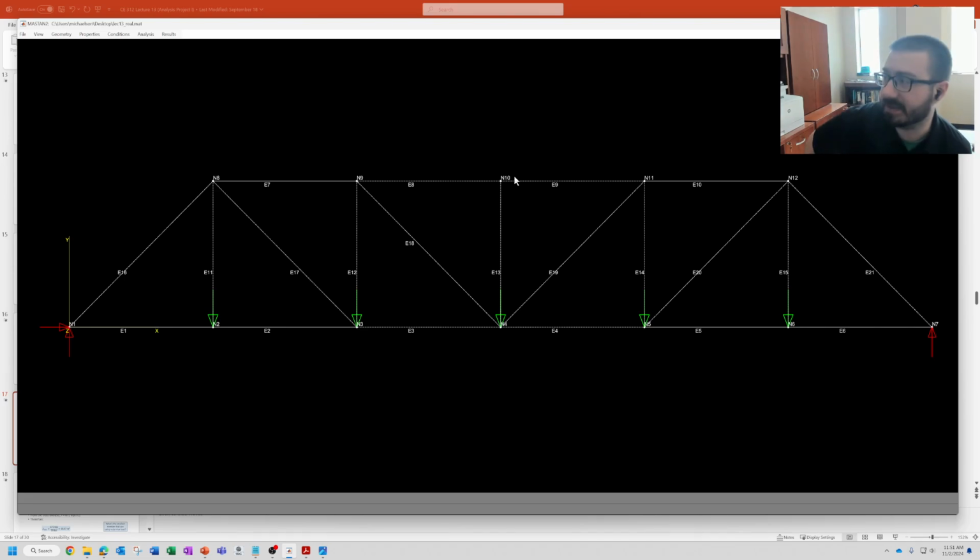Okay. One of the reasons for that is that as you start iterating your truss design and changing the member selection, it does not affect the forces in the truss members. So it doesn't matter if any of these members are W12 by 14s or W12 by 96s or whatever. The forces in the members won't change, because method of joints and method of sections on a determinate structure isn't affected by what the member's made out of.